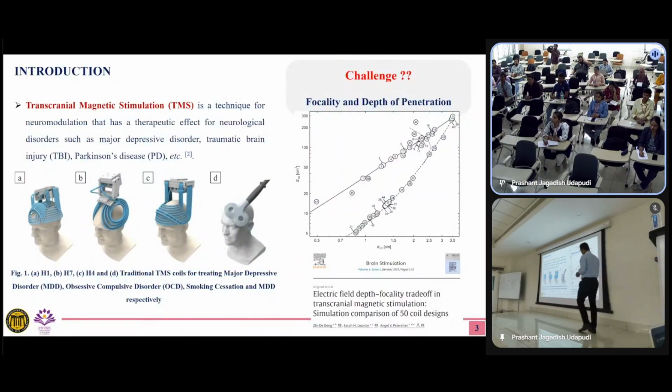So these are their commercial coils. In all these coils, there is no magnetic material. It's all copper windings. But the magnetic researchers know we can change the way magnetic fields are directed by using magnetic material. If you have high permeability, all the magnetic field will come through the high permeability material, right? So if you put a core here, instead of going below the coil, the field will go through that core.